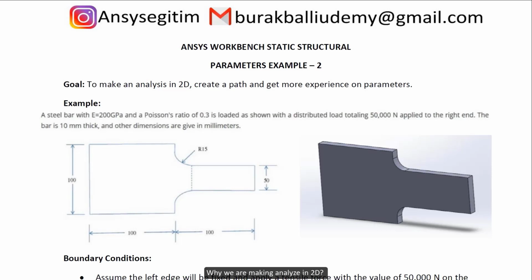Why are we making the analysis in 2D? The first and the most important reason is to reduce the nodes number and the elements number, so we can reduce the analysis time. I mean solving time. We can get the same results in less time without too much effort. How can we decide whether we'll use 2D or not? When you look at the front face, if you extrude it, there will be no change along the extrude. I mean, there is no difference between 3D and 2D beyond thickness.